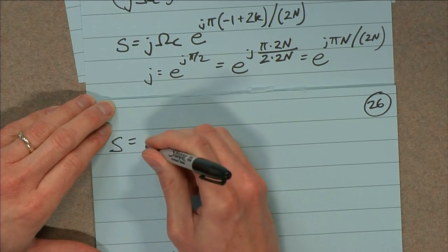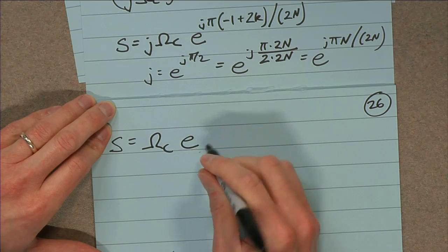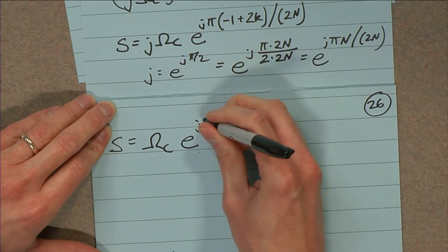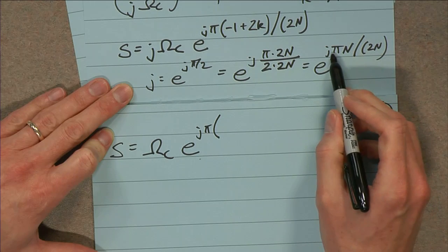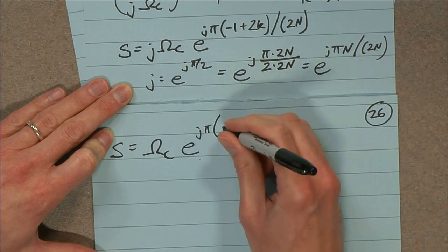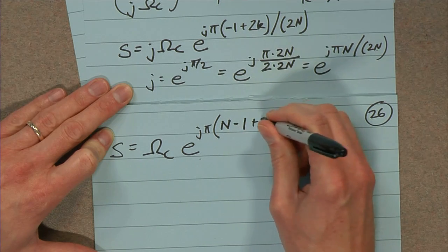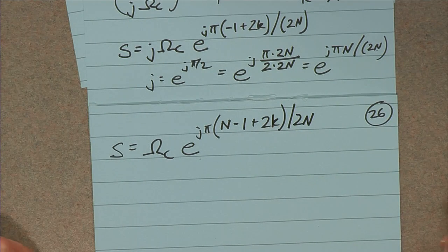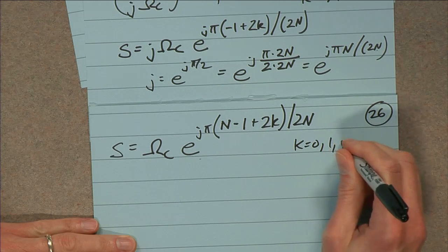So S is now omega c, e to the what? We have j pi n. I'll factor out the j pi, just like I did here, make my life easier. But if I factor out the e to the j pi, that leaves an n over 2n, which is good. I got the 2n there, so that means I'll just bring this n up here. And then I've got to carry the rest of this. Minus 1 plus 2k all over 2n. And now let's take a look at what k can be. k is 0, 1, 2, ...